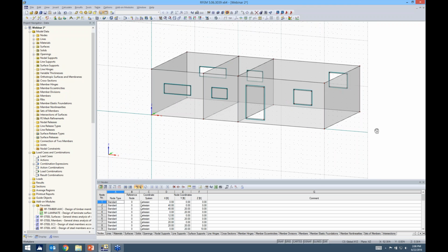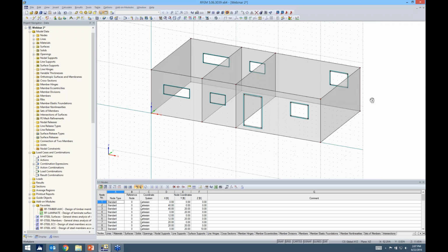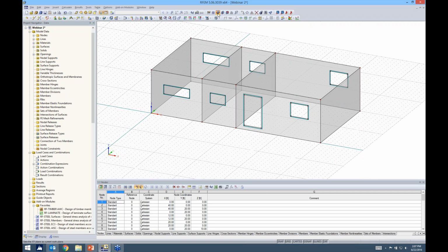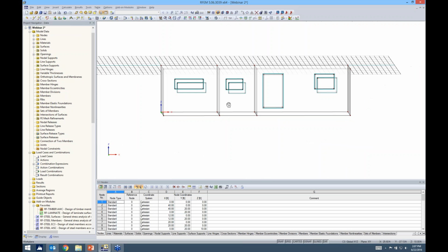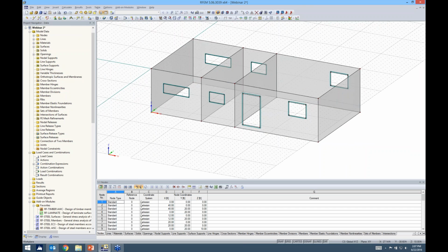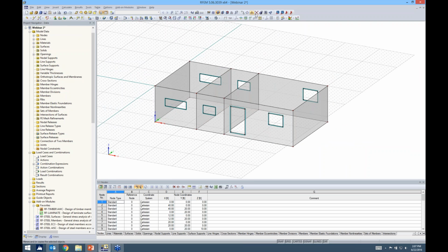Okay, so now that we have this defined, I'm going to change my line grid now for my floors. I simply change the work plane again, and you'll see how quickly I can define my different origins, and now I'm at the top of the structure. We have this other button up here, and what this does is I can select all of the model.